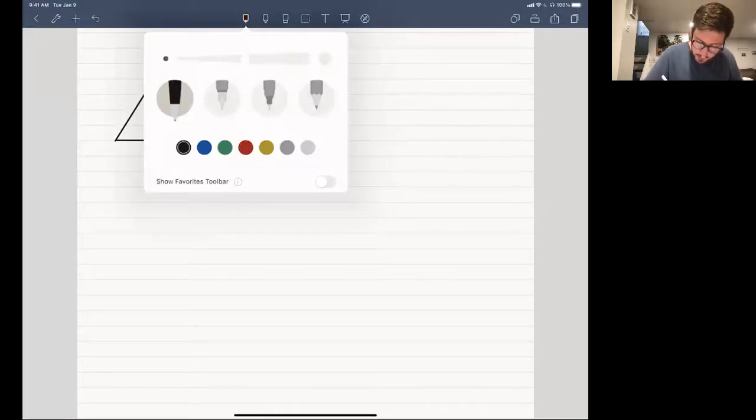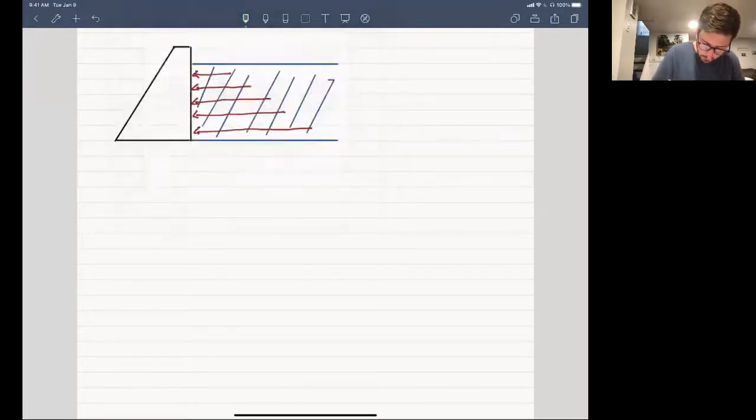And we can actually characterize this perfectly. So if we say this depth here is, say, H, there is a formula that gives us the pressure that's going to be exerted on this dam. And this formula is very, very simple. It's linear in the depth. And it says that the pressure is equal to 62.4 H. Think about how interesting that is, right?